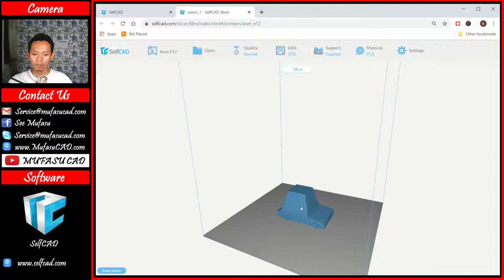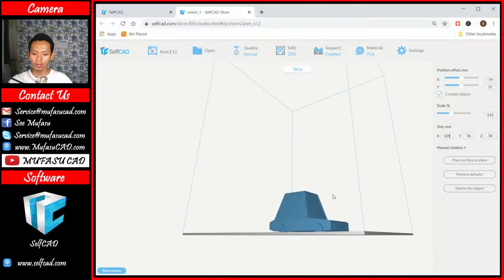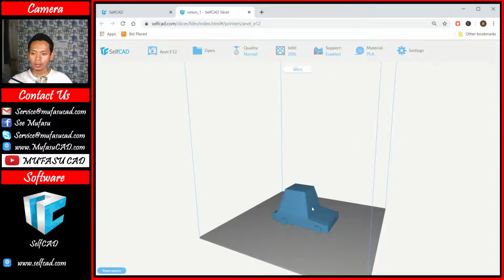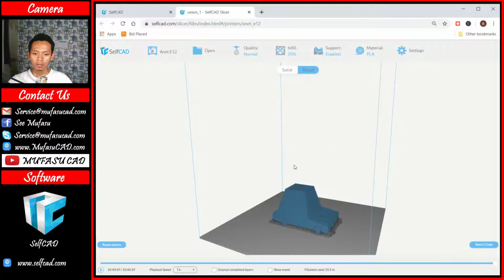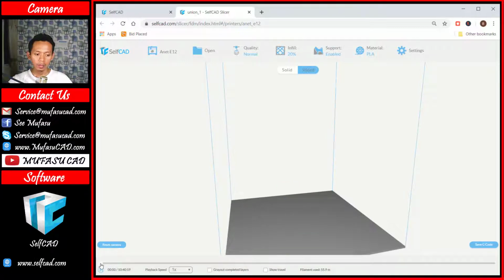Okay, you can click this object and then you can set the size. Like I will change the size to 125. It will be bigger. Now to slice these 3D models, you can click this slice button and we're waiting for the slicing, preparing, and then it will create the slicing. Okay, now you can save the G-code here. You also can preview the printing animation with this play button. Okay, this is the printing animation.